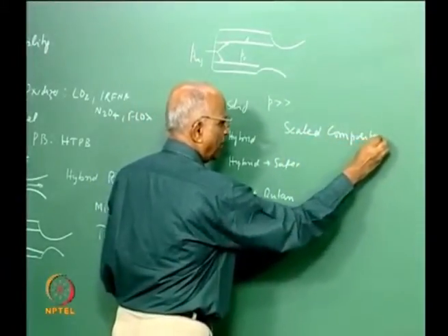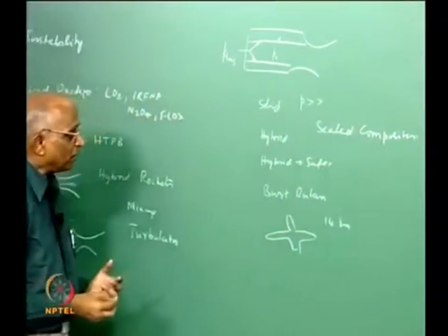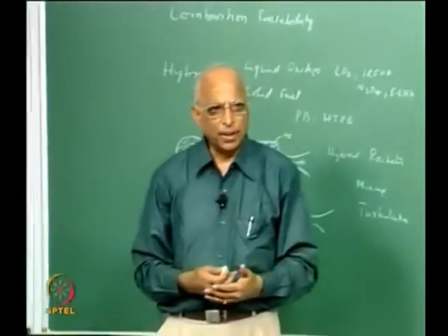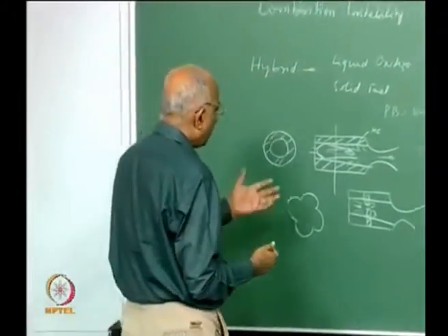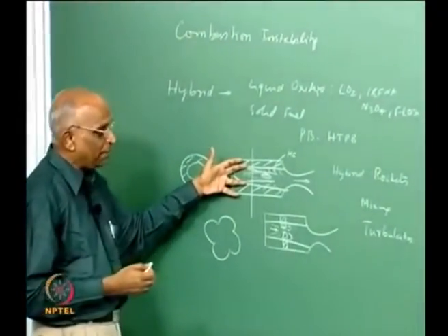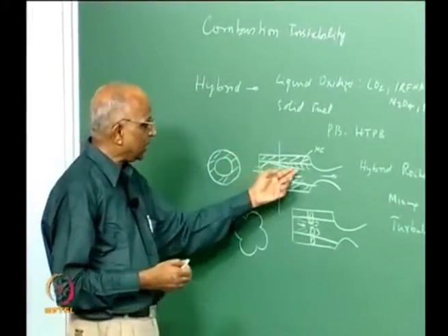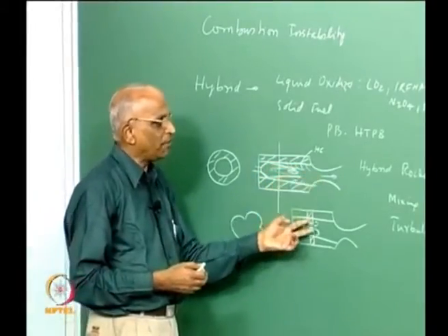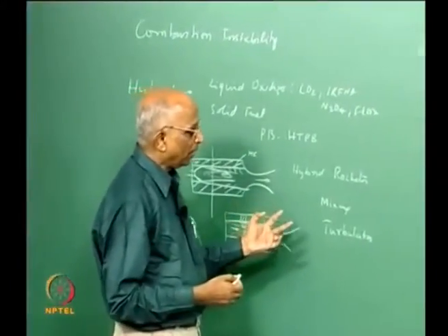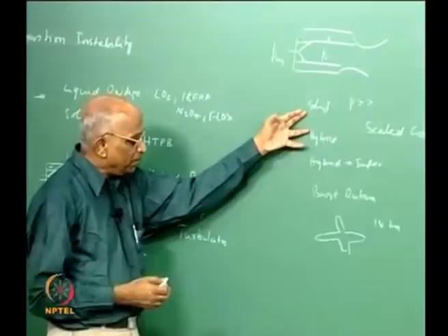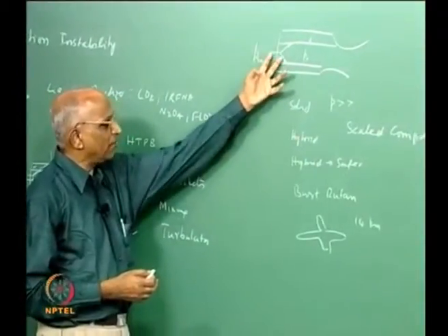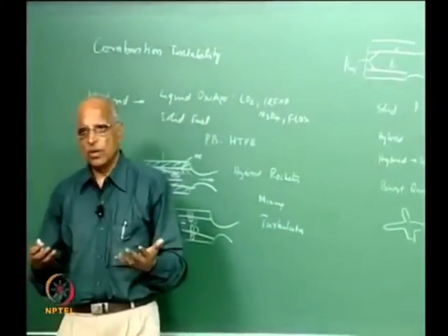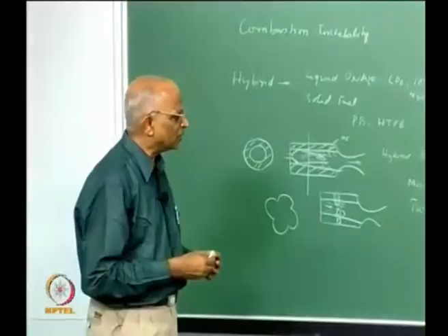Last week the launch pad was officially inaugurated in the desert in California. I think this is something which we can keep in mind. Therefore, I would say hybrid rocket has not been very much used in practice. However, it is something like a convective heat transfer which vaporizes the propellant, mixes and burns. It has lower performance than a liquid propellant rocket. However, it is safer than many of the other types of rockets because it is self-regulating, and it is finding increased applications. I do foresee much more applications for hybrid rockets in the years to come.